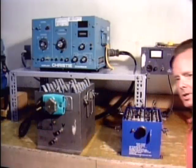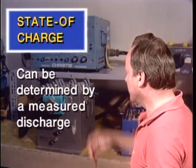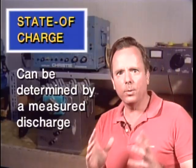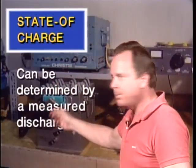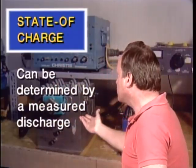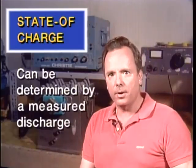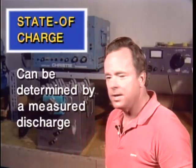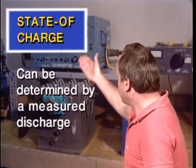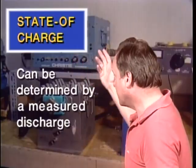Now, here's a question I do not like on the FAA written exam. They ask you, how do you determine the state of charge of a NiCad battery? And the answer, the only one that can possibly be a correct answer, is that the state of charge of a NiCad battery can be determined by a measured discharge. Now what they're talking about is you discharge the battery at a specified rate and measure its ampere hour capacity, then recharge it. Now that might be a way to tell the condition of the cells of the battery, but I don't think it's a very good way to determine the state of charge.